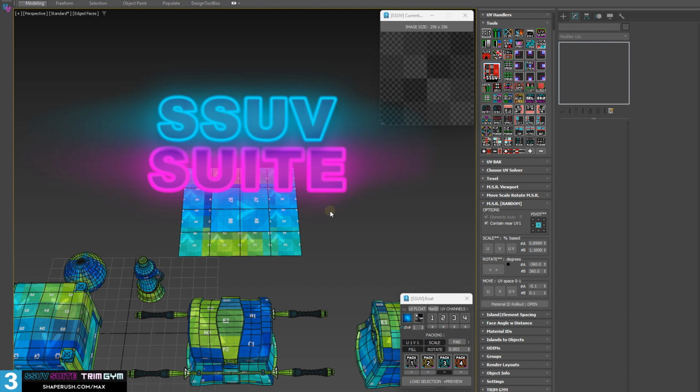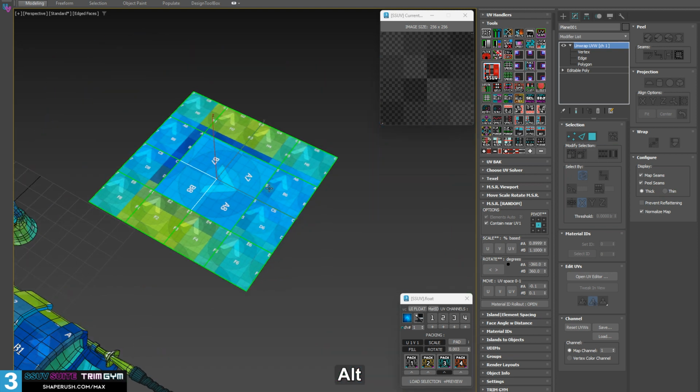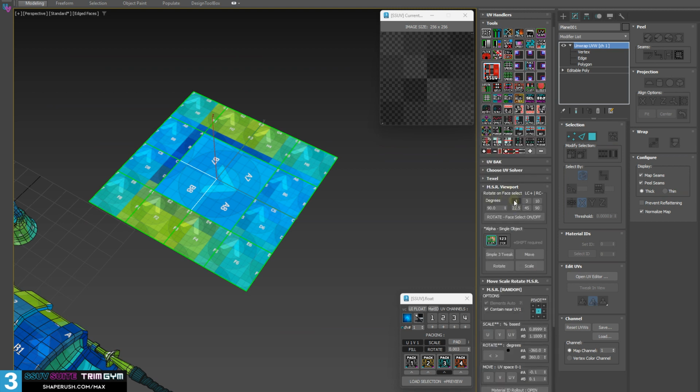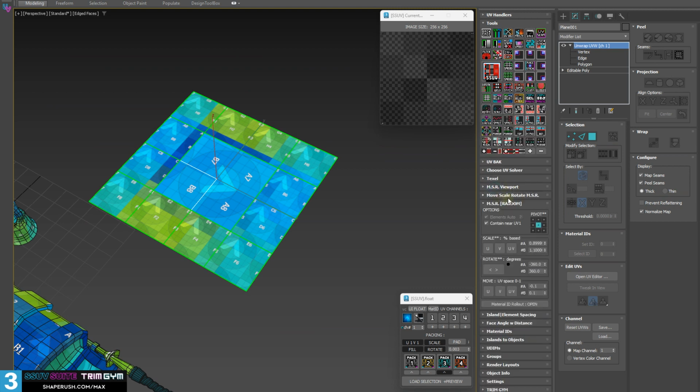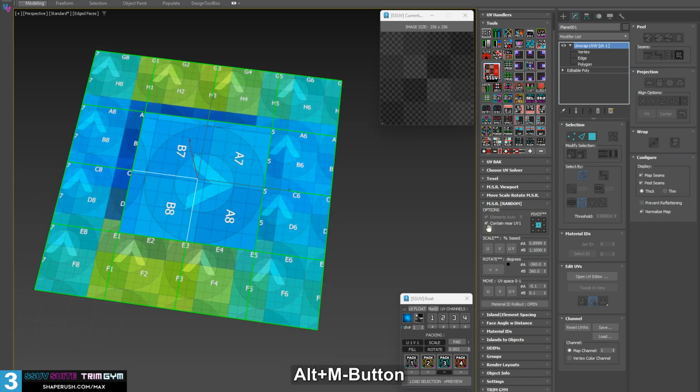And now we have another move, scale, rotate panel, but this is random. Let's get into this. Okay, so we could do somewhat random movement earlier based upon the selection of the rotate on face select, but we're going to get a little bit more into this, okay? So we're going to contain things near U1, V1, because if we do not have this selected, then when we're moving things around, things could shoot way off into UV space, and we do not want that to happen.